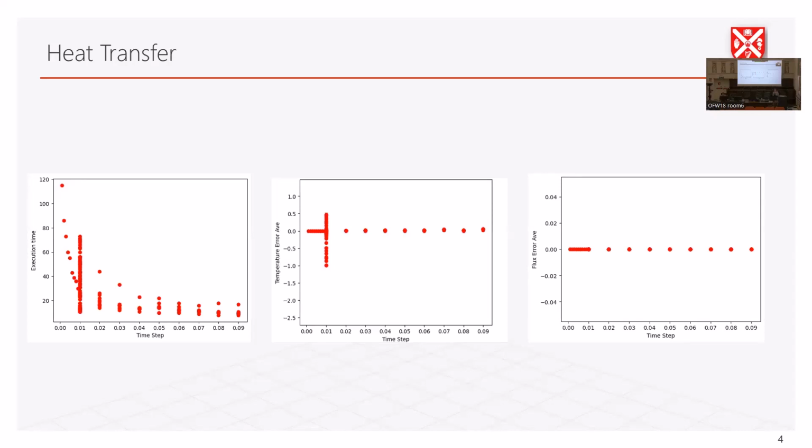As you can see here, when I do the shorter one, of course, there is longer simulation time, but you can't actually see much effect on the results. So it's true that if you have a range of different times, you can still have acceptable accuracy in the result. You don't have to put all of the parameters at the highest precision.